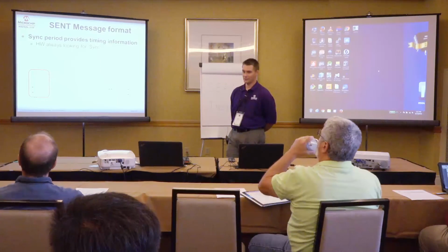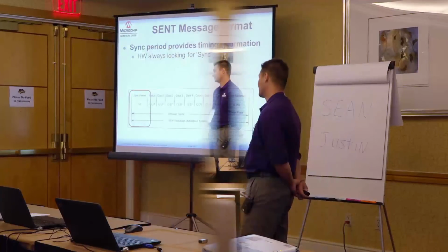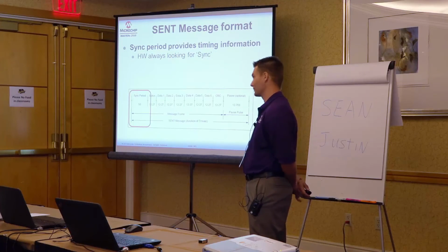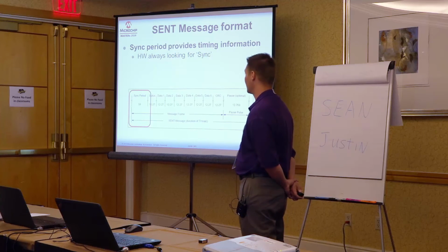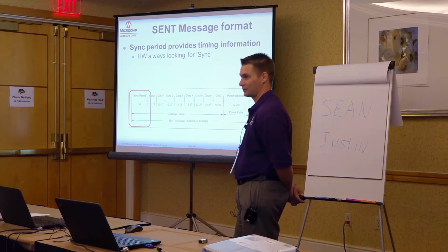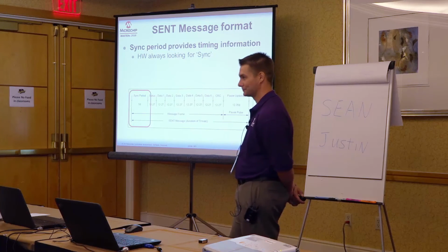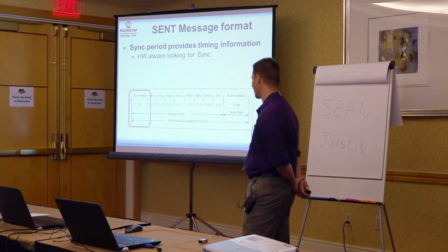So we're going to look at the message format real quick. It starts off with a sync period, which again is for the clock synchronization. And the hardware is always looking for this sync pulse, so if something gets reset or something gets corrupted on the bus, it can find a new sync pulse and it won't hang somewhere stuck in there looking for the next data nibble.